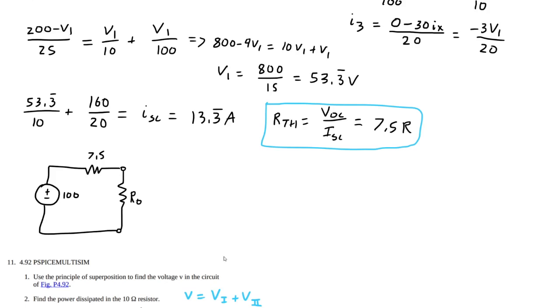We're going to plug this back in now. So if we have only one current in the circuit, call it I, and I is equal to V over R, and R is 7.5 plus RO, so let's do power equals I squared R. We know I is going to be Ohm's law, so 250 equals 100 over 7.5 plus RO, squared, times RO.